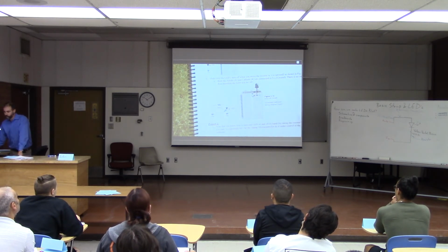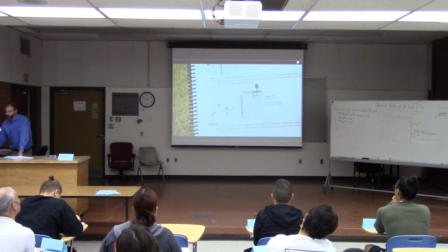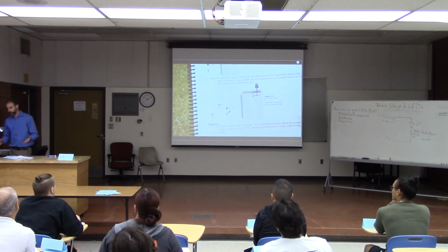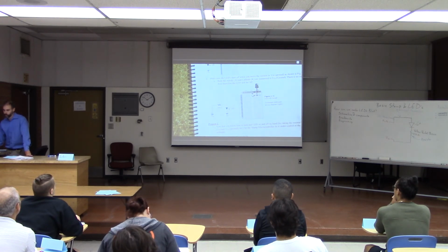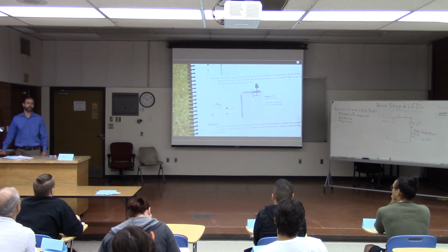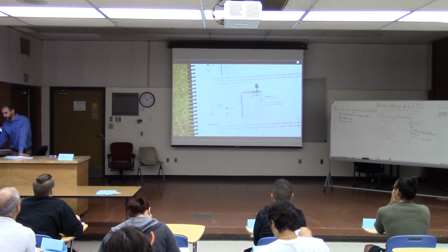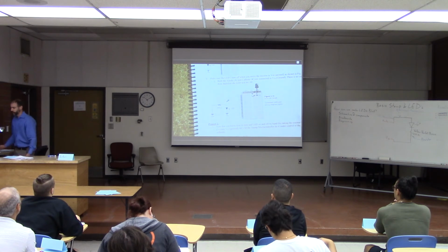With this one, it's kind of funny. They've got both sides of the circuit hooked to VSS. So here, there's not really any pressure pushing the electricity to flow through this circuit. So if you hook this circuit up just right, then you'll notice that absolutely nothing happens. Okay? So if you hook this up, this just shows you that the LED stays off when you hook it up like this. Okay?